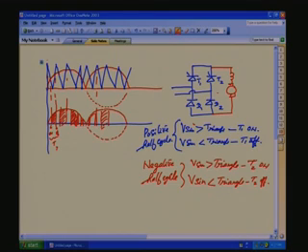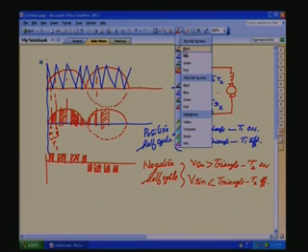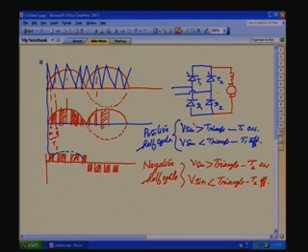But what is the advantage here? Because of the pulse frequency, how will the input current waveform look? Whenever T1 is on, you have the input current like this. When T2 is on, we have the current like this. Sorry, when T1 is on, it will be like this. That is rectangular pulses. On the negative side, you have it like this. The fundamental will be like this, and here also we have unity power factor.